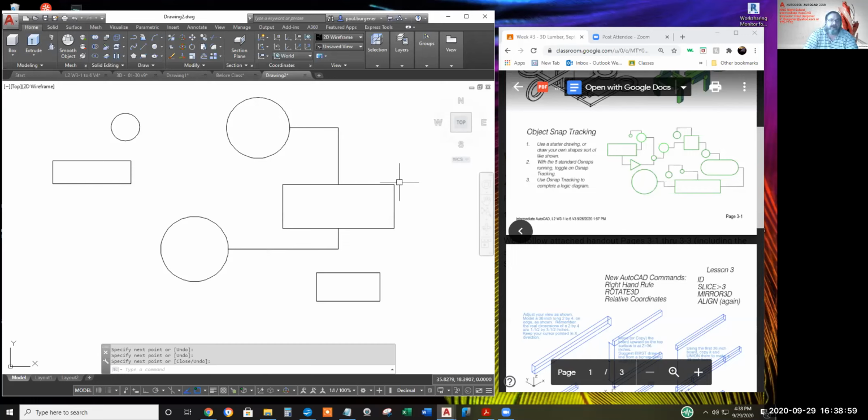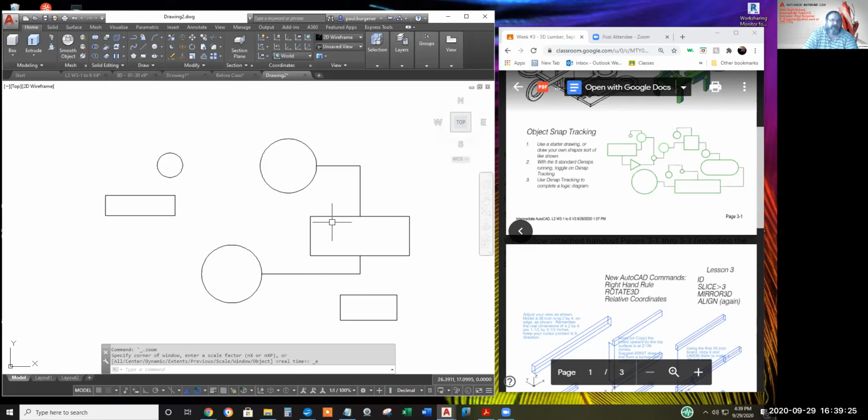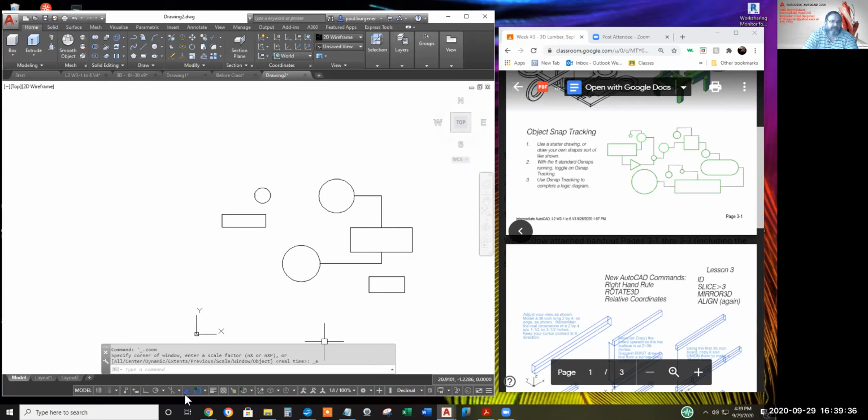I'm trying to remember, I think back in the day I'd also draw a line like right here and begin a line there. And delete. When I was doing floor plans, I'd almost start acquiring and clicking while humming to myself, without even thinking about it. So that's object snap tracking.